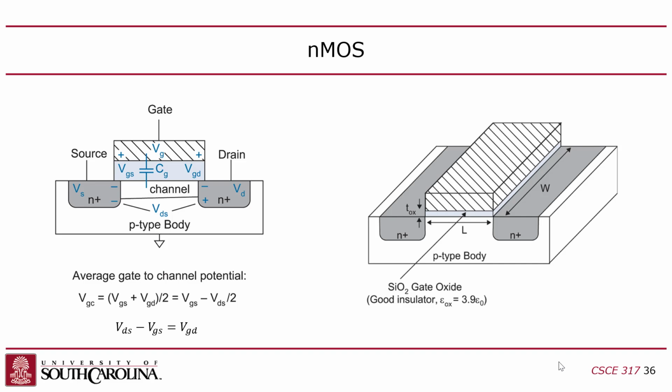So what that means is that if I want my circuit to be faster, I just make the transistors wider, right? So I can increase this width. By increasing that width, I can drive more capacitance faster. I can charge and discharge faster. That's one of the tricks you can play. Usually the width is 5 times the length for an NMOS and 10 times the length for the PMOS, generally. So if this is a 45 nanometer length, then the width will be 450 nanometers if it's a PMOS, and half that for an NMOS.